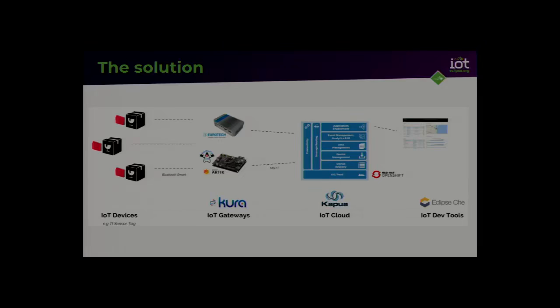In my case, it's a very simple app/plugin that will, every 5 seconds or so, discover all the sensors in proximity, depending on how many packages I have, and for all of them grab the telemetry data and send the data to the cloud. And on the cloud side, what Kura does is basically use MQTT as the protocol for the communication.